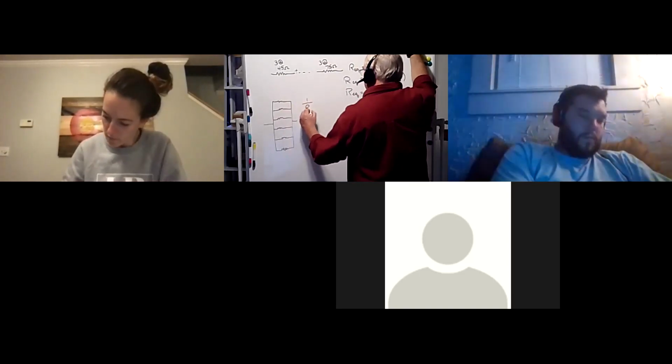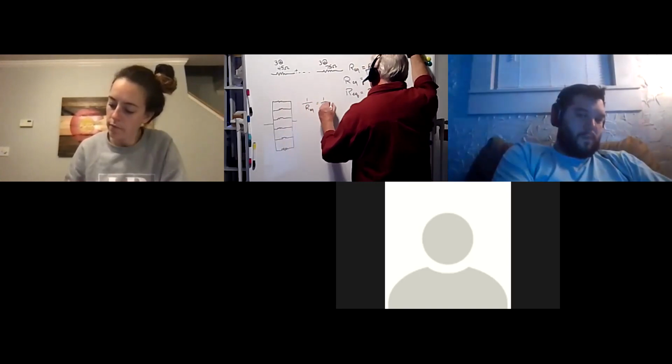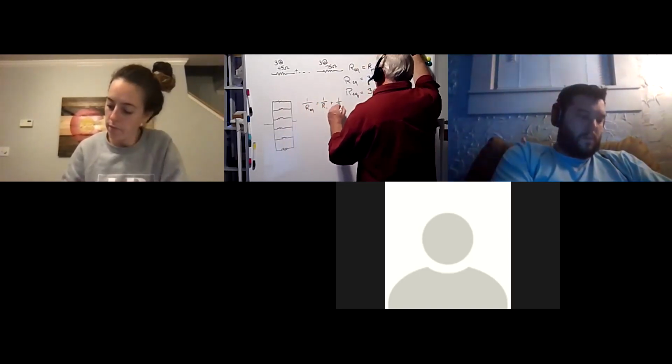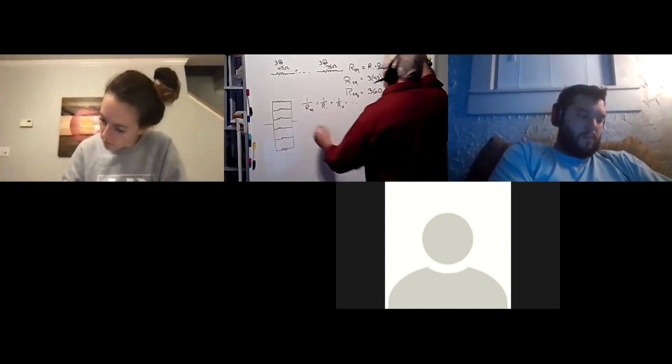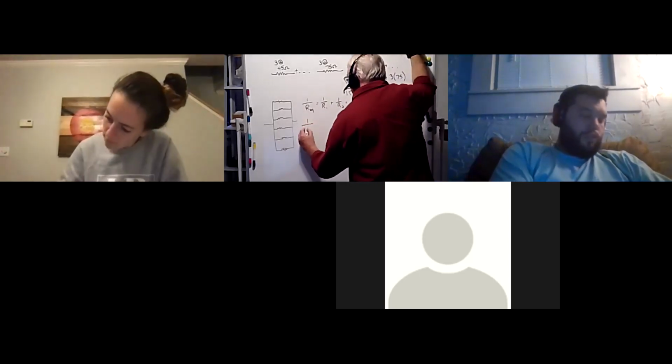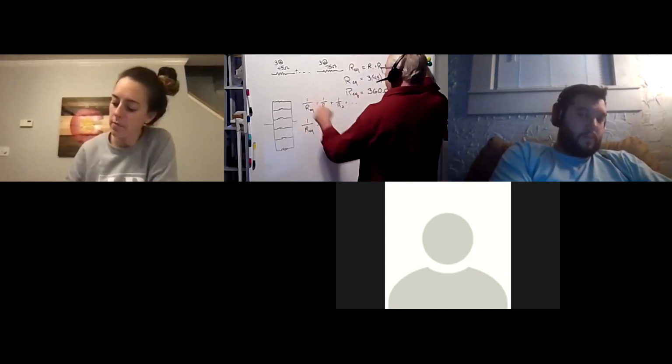So 1 over REQ is equal to 1 over R1 plus 1 over R2, and then repeating. So when I do it for this example, 1 over REQ, well, I have 3 45s.